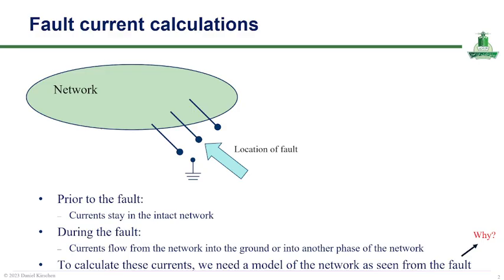Okay, these devices must be capable of detecting and interrupting fault currents quickly to prevent equipment damage, maintain system stability, and ensure safety. So the magnitude of the fault current depends on factors such as the system voltage, network configuration, and the equivalent impedance seen from the fault location. Therefore, accurate calculation of fault current is a fundamental step in power system protection and planning.